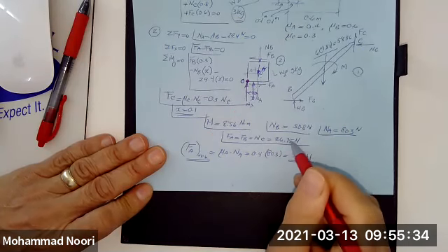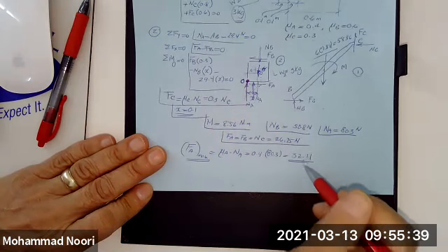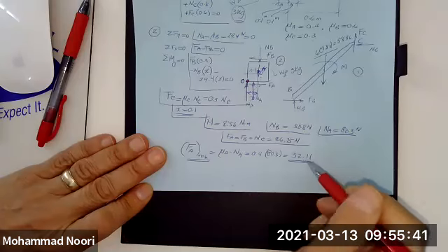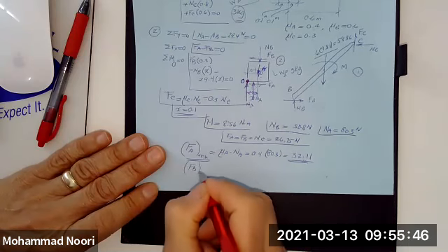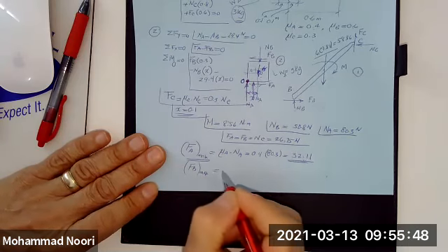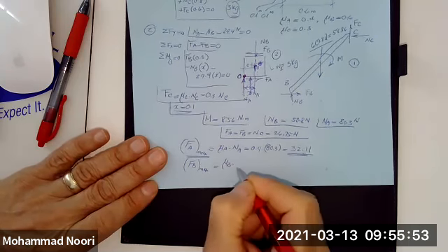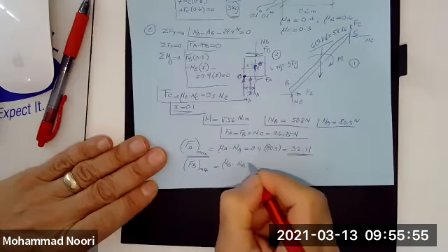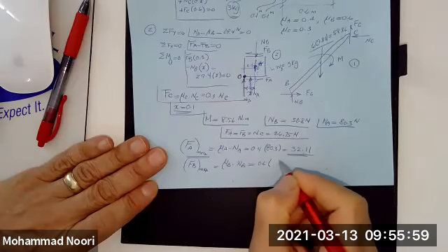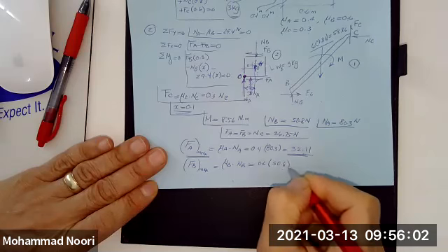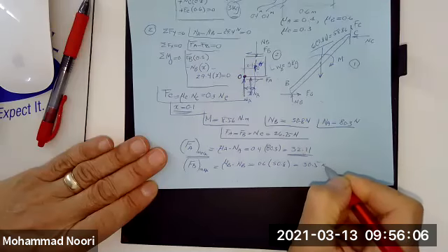Whereas the force that we need to keep this in equilibrium should be 26.75, so it's less than the friction force. So the friction force will keep this in place. How about at B? If any slippage takes place, the maximum friction force that would be generated there would be mu B times NB, and that is 0.6 times NB, which is 50.8, and that gives me 30.5 Newton.